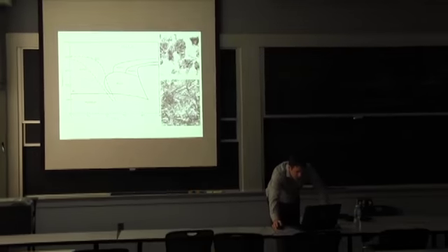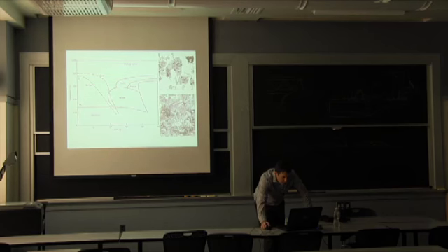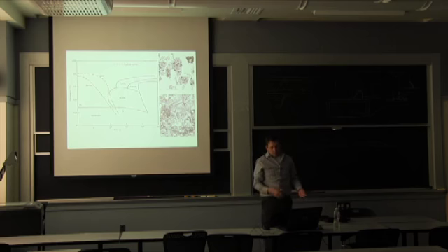So what you see is you start at 800, and the horizontal axis is time. So over time on the surface, you manage to cool low enough that you reach the martensite transformation before you get into other phases, but not in the core. So the core, the other curve, gets essentially a softer interior than the surface because it's going to hit that bainite. A bainite phase, I don't have a picture, but it essentially has some form of cementite in it, but it's very small. And that's why it's stronger than the pearlite.